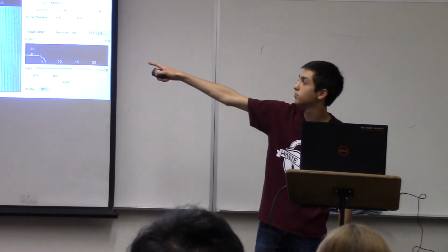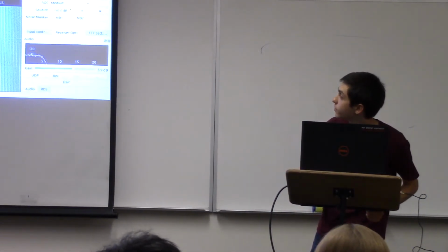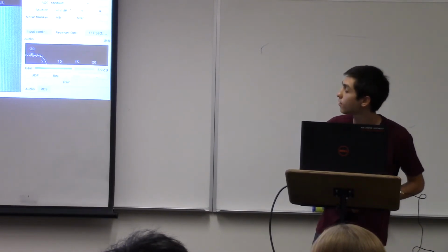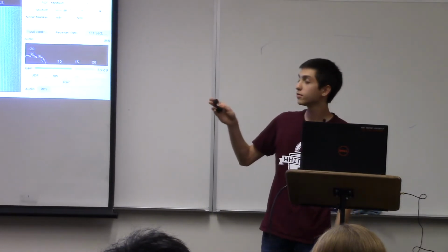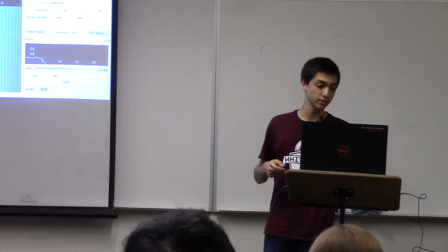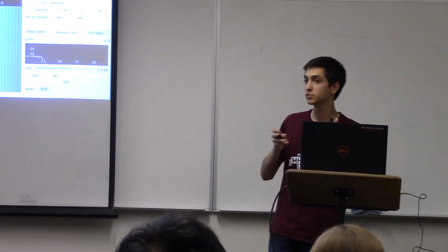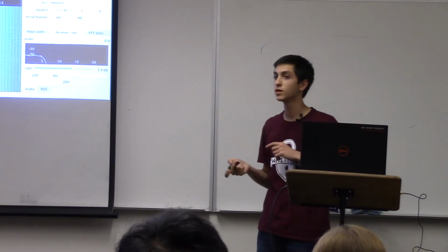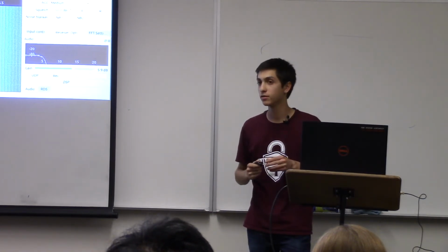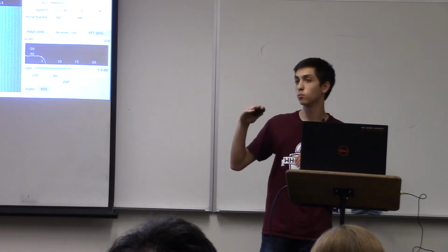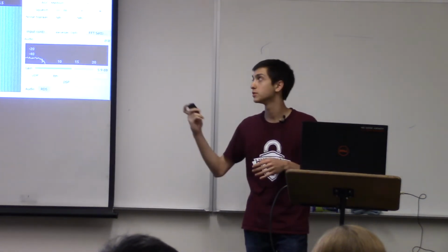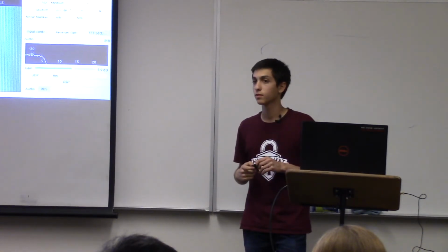So you see that signal, let me get the red line to it. Like right there. Well, what if we jam like 2 hertz, like a few hertz above? With a precise enough device, we'd still be able to differentiate between the 2 signals. But the receiver's probably not as fine-tuned. So it's going to see both of those signals as one signal, and it won't be able to recover the code.